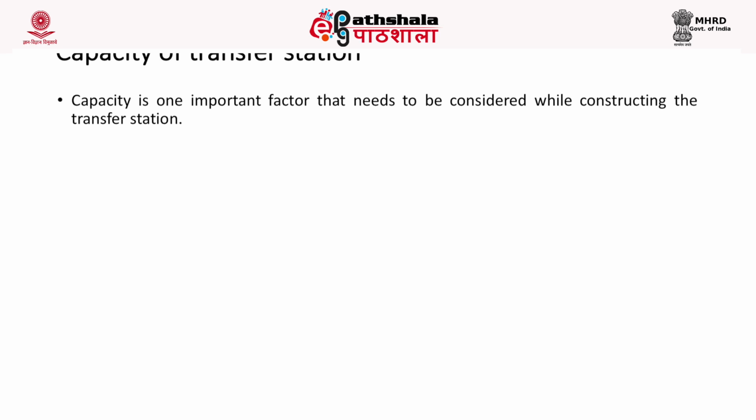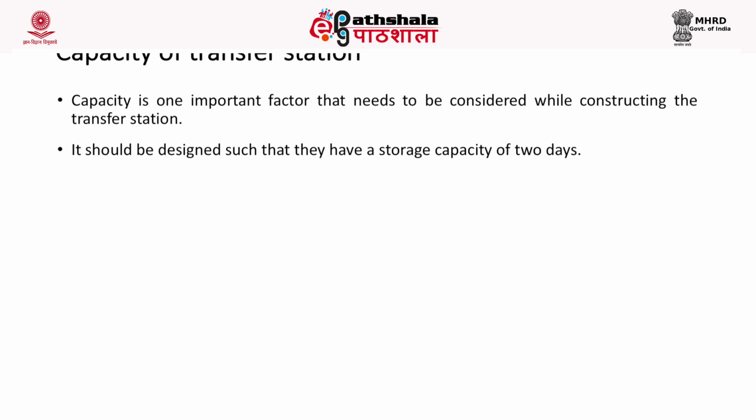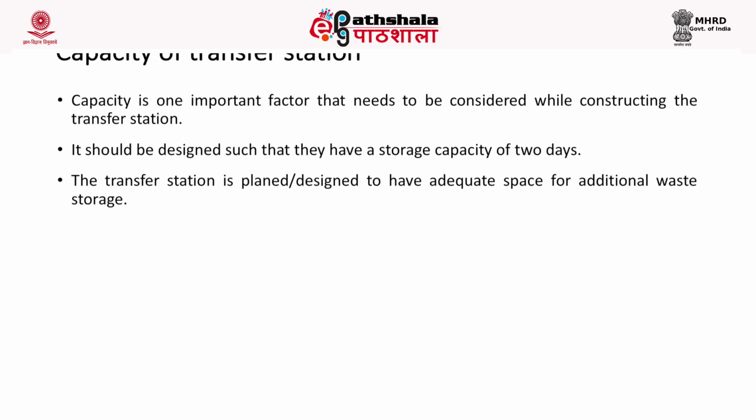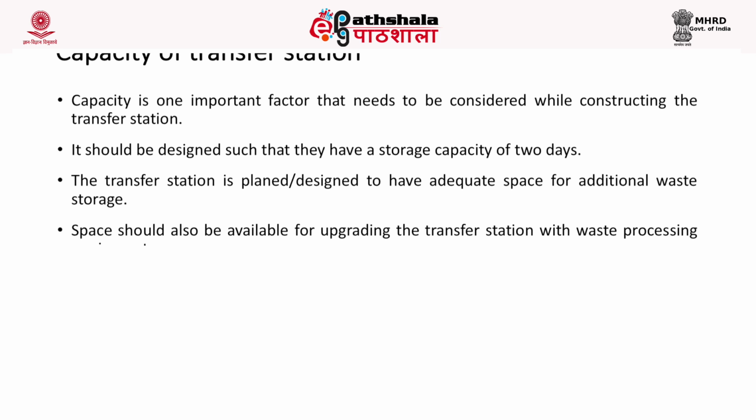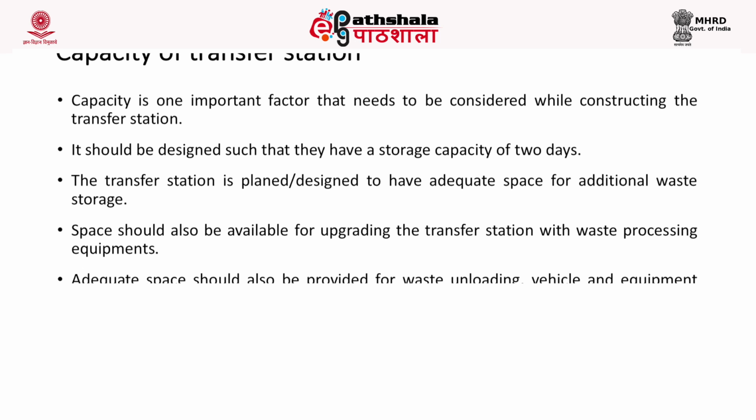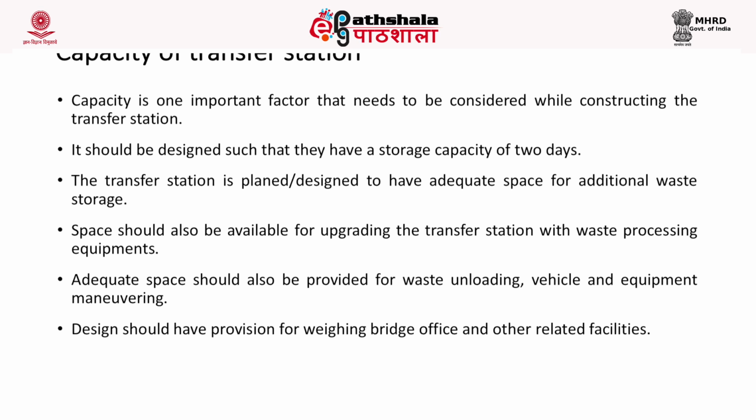Now, the capacity of transfer station is another important factor that needs to be considered while constructing the transfer station. Now, it should be designed in such a way that it should possess a capacity to hold or store the waste for 2 days. The transfer station is planned, designed to have an adequate space for additional waste storage. Also, there should be space available for upgrading the transfer station with waste processing equipments. Also, there should be adequate space for waste loading, vehicle and equipment maneuvering. The design should have provisions for weighing bridge, office and other related facilities.